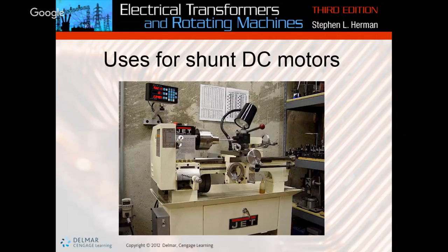The reason, of course, is that when we're talking AC and DC, we can plug an AC motor right into the wall any place, and it's always going to run at 60 cycles a second. The DC motor we can't plug into the wall because we don't have the right kind of voltage. So we have to add a bunch of different stuff to turn the AC voltage we have everywhere into DC voltage. So keep that in mind if you're ever in a spot where you think, man, Brian said you can control the speed on these really easily. Think about what you're doing, okay? Don't just run out and grab a DC motor if you need to run a pump in your well house out at your house.